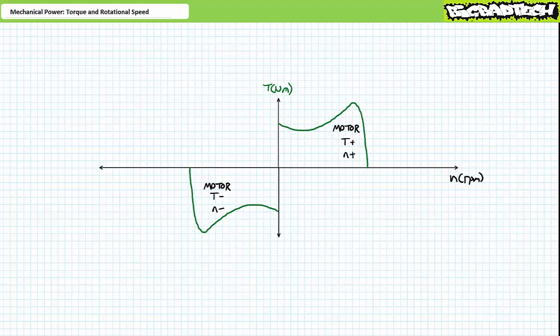Here's where people kind of lose their minds. You note this chart as presently illustrated is for speeds below the synchronous speed, i.e. the speed of the rotating magnetic field produced by the stator. What happens if some outside force, like moving wind, falling water, a rotating engine, or expanding steam, i.e. a prime mover, grabbed the shaft of the rotor and started spinning it faster than synchronous speed? We might get a more comprehensive speed-torque curve that looks something like this.